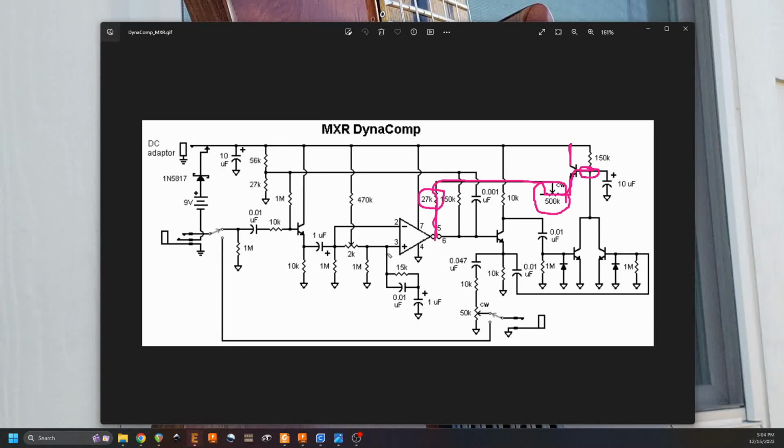So that's how this envelope detector and OTA stage work together: we have an output signal that gets negative swing rectified, positive swing rectified, filtered into a DC voltage. The DC voltage goes through a resistor that limits the amount of current we sink, and that current goes back into the OTA to change what its amplification factor is. Okay?